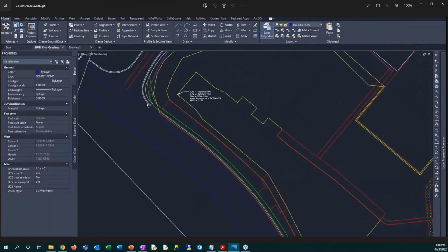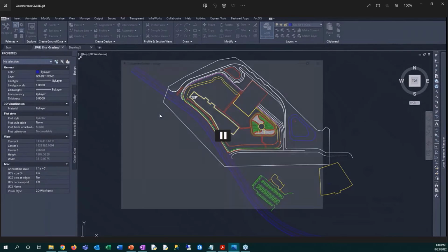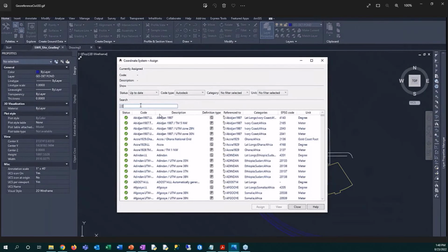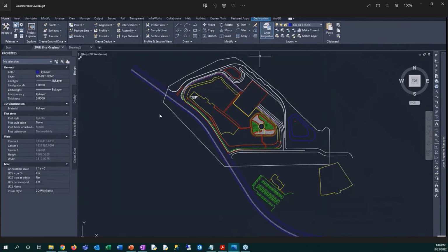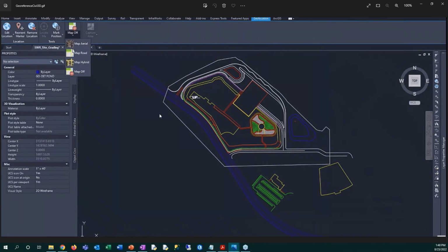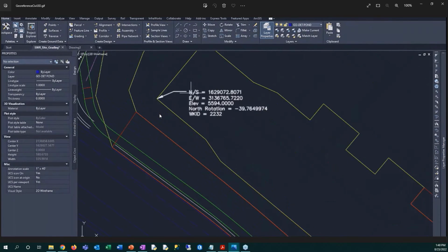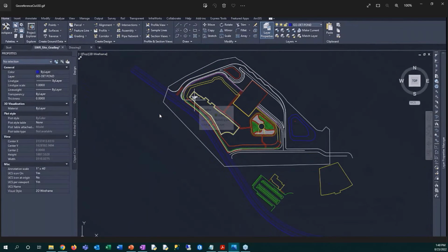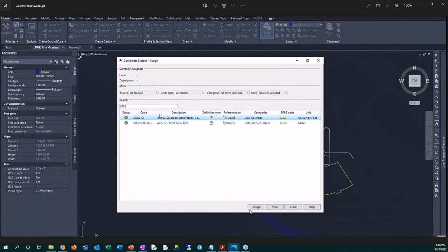And we'll see how this is done from Civil 3D. So we have our referenced point there. We're using the Map CS Assign tool. We're selecting our map projection based on a search of well-known ID, assigning it, and then we're going to go ahead and add a map to our project, and it appears in the proper location. So that's our first workflow here from Civil 3D to be able to make that first connection between GIS and BIM data, which is going to be assigning that coordinate point and then the associated coordinate system.